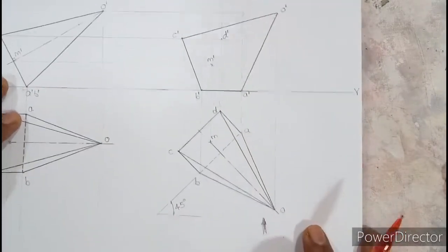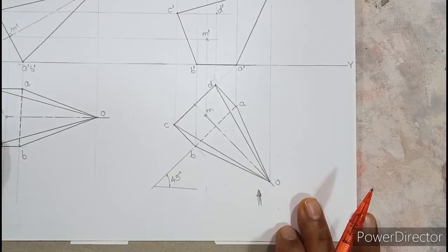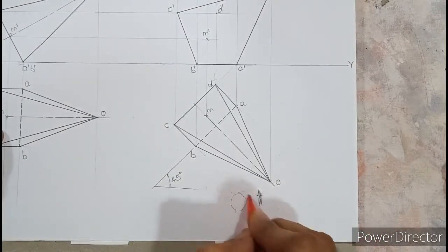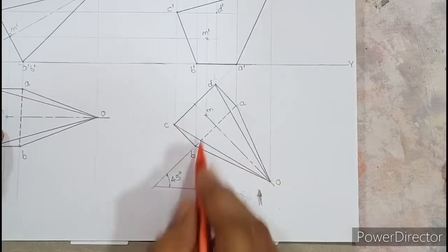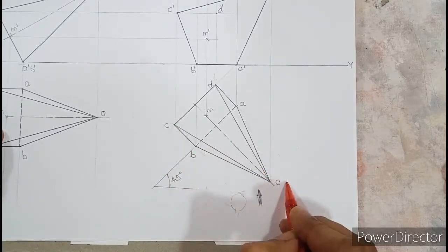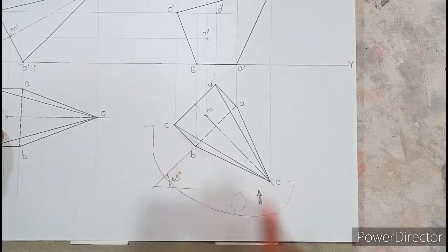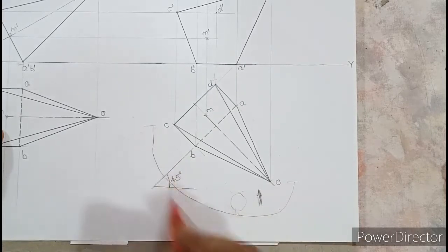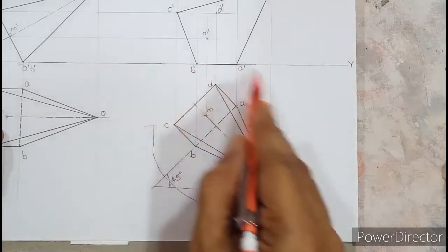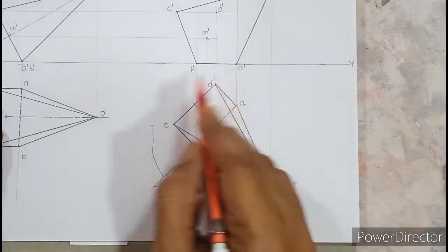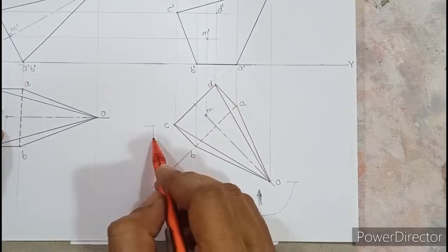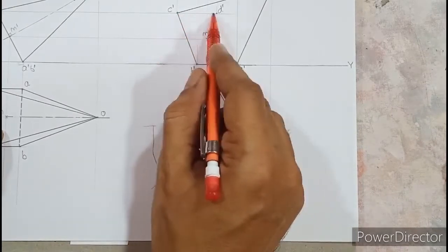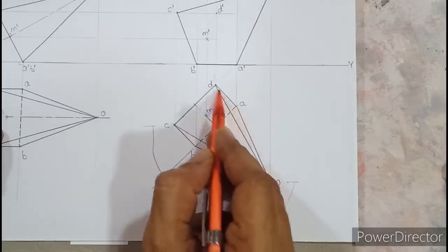What is another way to look at it? Suppose you switch on a bulb, there will be parallel rays of light, for example. You can see everything from O to C, isn't it? From O till C, you can see everything because that is within 180. You cannot see what is beyond that. So carefully look here. From O to C you can see everything, and hence you cannot see CD. C to D is not seen, so it is hidden. You cannot see D to A, and therefore it is hidden.